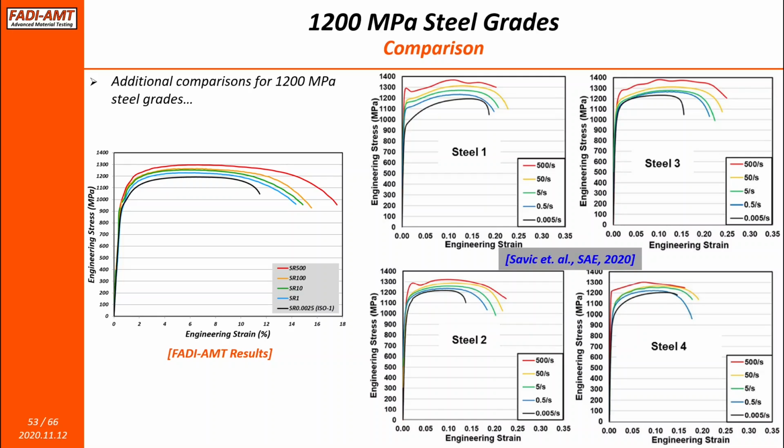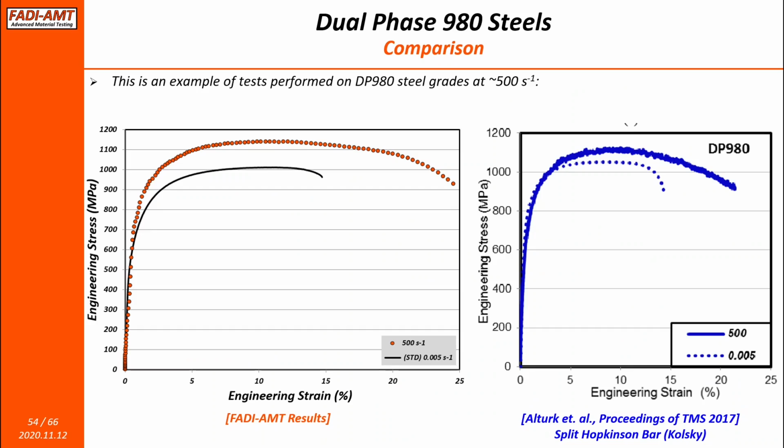What we always tell our clients and also our colleagues is that don't focus too much on the quality of the stress-strain curve in the elastic region for high-speed testing. You should just focus on the plastic. And that's where the curve quality basically should be good.